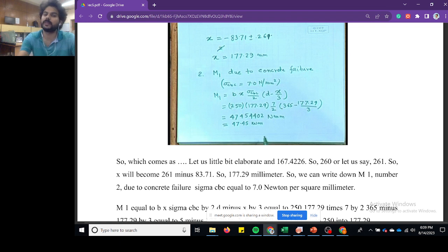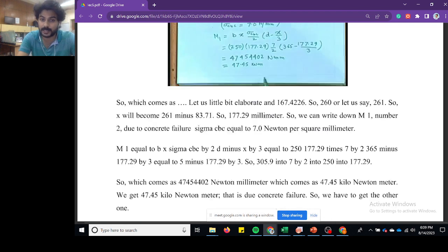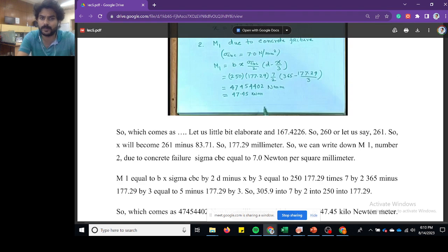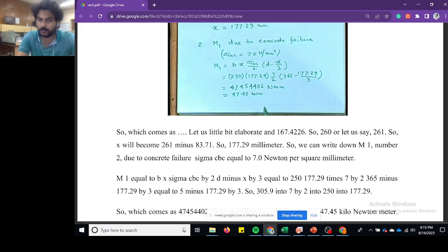Total area of the steel we have put in, and then we have calculated the moment of resistance. This moment of resistance should be greater than the bending moment coming onto the member. How does the bending moment come onto any member? When we apply load to the member. That load may be due to self weight, live load, wind load and earthquake load, whatever combination we have seen in the last class. Okay, so this is a solved example. Now we'll go to the different types of questions, different types of solved examples generally asked in the working stress method.